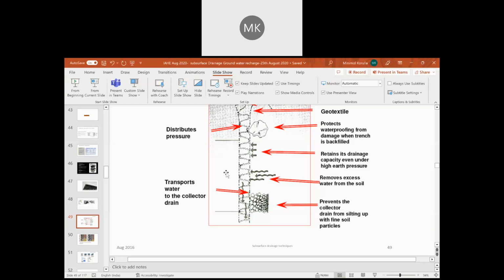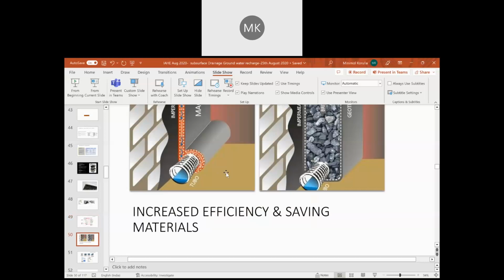It should be greater than 2.2 kilonewton, and in-plane permeability at hydraulic gradient i equal to 1 is defined for two pressures, 100 kPa and 200 kPa. At 100 kPa, it should be more than 0.6 liters per meter per second, and for 200 kPa, it will be greater than 0.55 liters per meter per second.